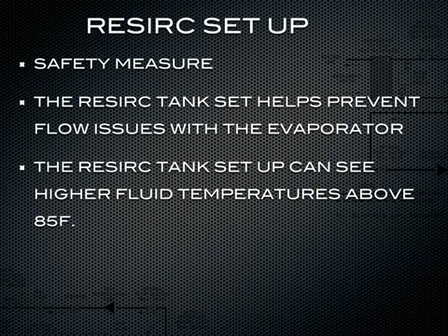You have the recirc pump servicing that evaporator, and you have the system pump. So as long as you turn your chiller on before your process and that tank temperature is brought down to, let's say, 55, that warm fluid coming back to the tank will always mix with that water, and the refrigeration system will not be affected because it's not seeing that warm fluid.